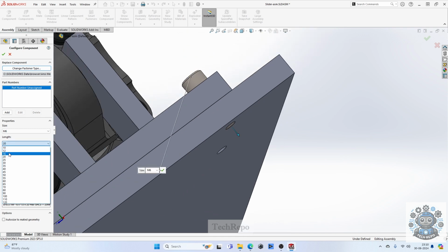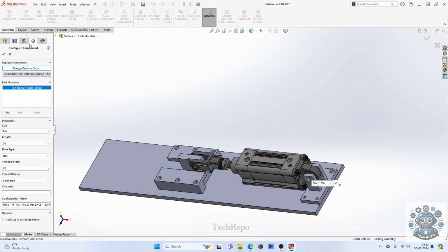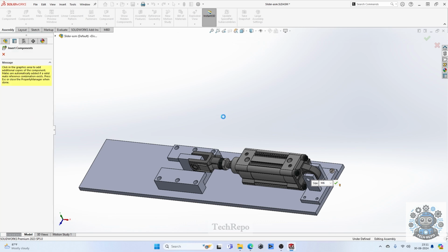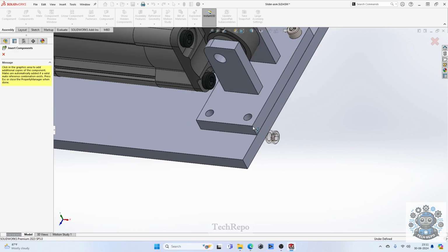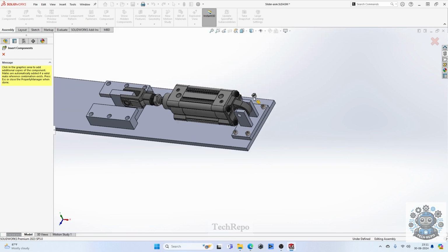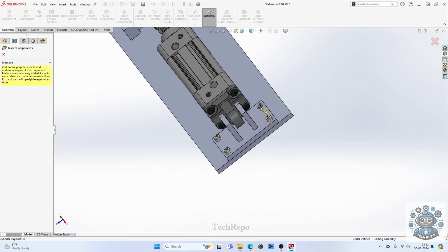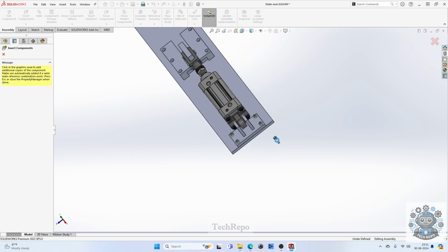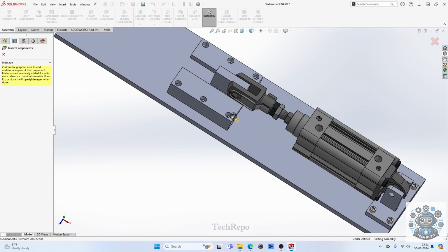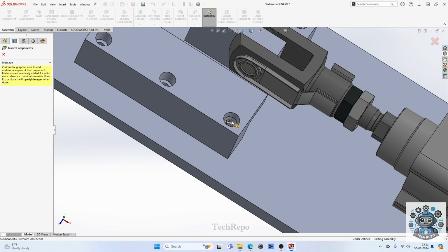Practically, generally for a bolt, the thread should be 2 times the size. That is, if it is M6, the thread length we define as a minimum of 12, and the minimum engagement for the bolt in the hole should be 1.5 times. So it's 6 plus 3, so a minimum of 12 mm of the bolt should be engaged on the thread. That is what we define.